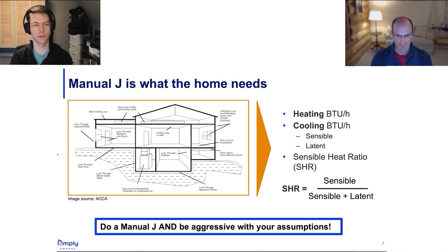We just taped a pod with Nate Adams on this topic. Since Manual J has some factors of safety in it, if then contractors are padding insulation and air leakage with more factors of safety, like they're being conservative, not aggressive, you end up with massively inflated loads. And then your Manual S is not going to be that helpful because your Manual J is totally off, like the two feed into each other. So that be aggressive is counterintuitive. At this point, we've onboarded hundreds of users to Amply, and we see this over and over again. It's a real mindset shift. Don't pad your stats. Be aggressive, be lean, and you'll get a better number to design a better system for the homeowner.